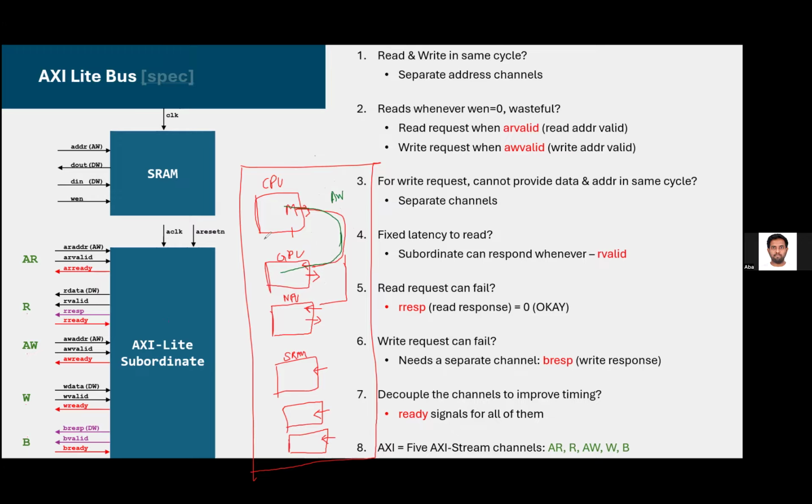It's pretty simple. The solution is basically you put a buffer in the AW channel. Over here in the AW channel, you can put a skip buffer. By putting a skip buffer, you are basically breaking the ready path, valid path, address path, and all of it, so you are registering them. Once you do that, your long path has become a short path. So now your signal goes here, and in the next cycle goes there.